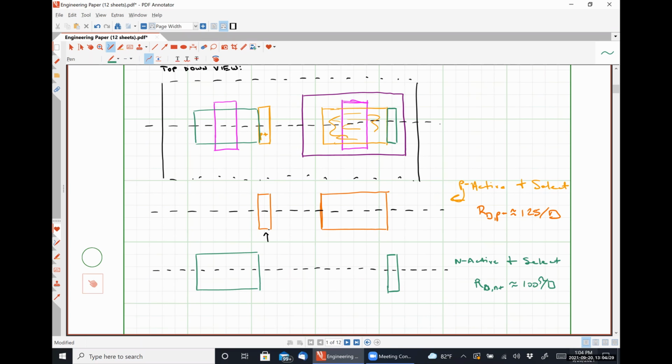So we have yet another thing that we can use for resistors, but these are typically used when you want very small value resistors, right? I say very small value, like you wouldn't do kilo ohm scale resistors with these because it would take up too much space. That's what the N-well or the high res poly layers would be for.